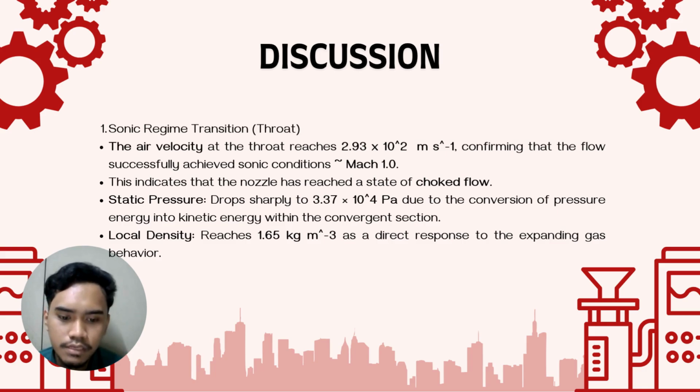Actually, if we key in the numbers into the formula, we are going to get a velocity of sound that is higher than 293, but why is it lower than the sound velocity? Because there is energy loss due to viscosity and friction. But somehow it successfully achieved sonic, because it is about Mach 1.0, and it indicates the choke condition at the throat.